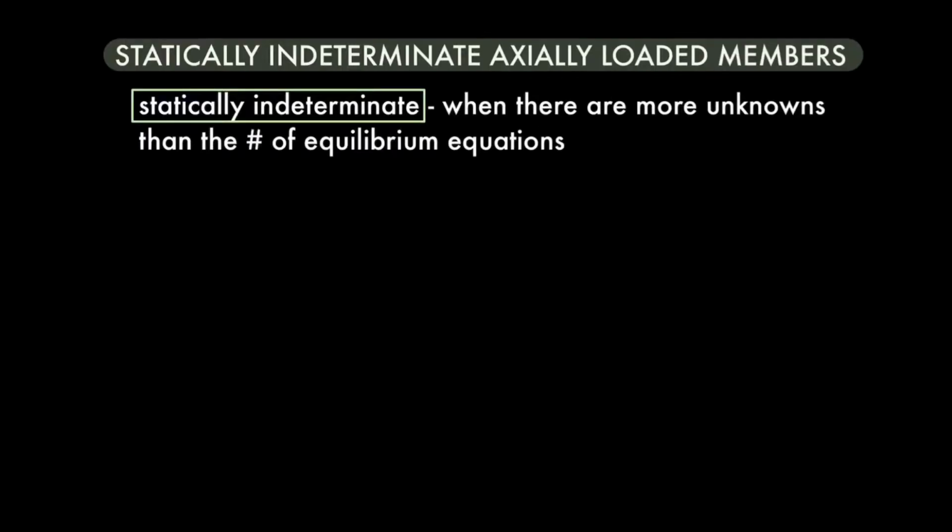Nice work! Our next key concept is the compatibility equation. We formulate a compatibility equation whenever we have statically indeterminate problems. But what does it mean to be statically indeterminate? Well, it's exactly what it sounds like. It means that it can't be solved with just the equations of equilibrium. In other words, there are more unknown reactions than the three equations we're used to solving with.